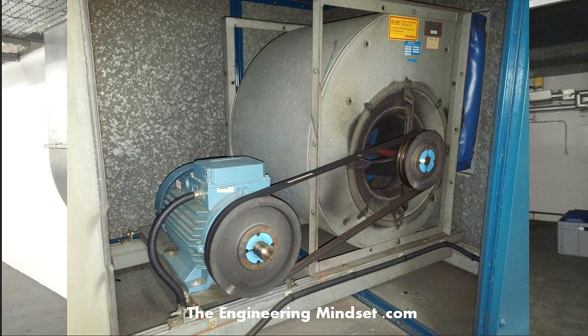And so that's the power unit there, and then this is the pulley here. This is the drive shaft, which is being spun by the magnetic field inside this induction motor, and that's rotating these pulleys and driving this pulley here, which is directly coupled to the fan blades inside this fan here. That's where the air is being sucked in, and then it's being pushed into the duct and then off into the space.